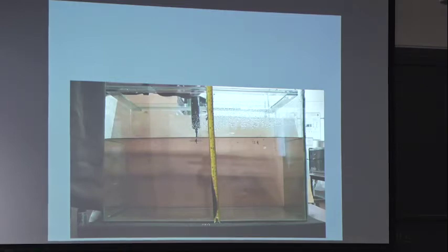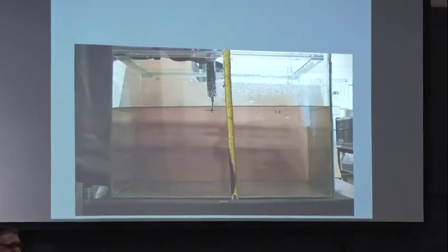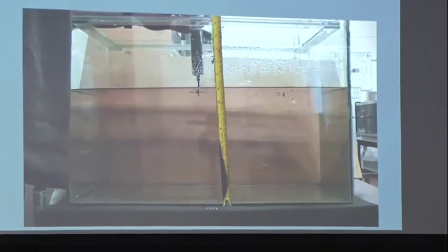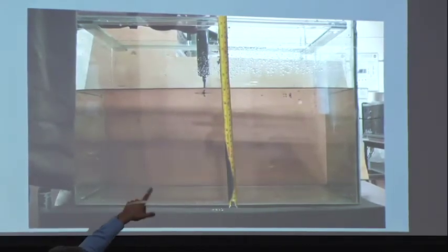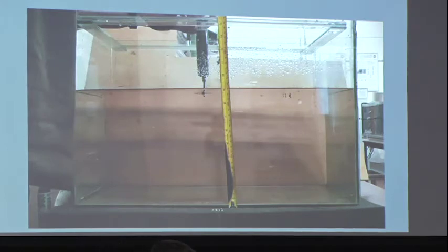Effectively you can reproduce with a salt a density gradient that is comparable to the density gradient that you will get in a fire. So what I'm going to be doing there is I'm going to inject 10 cubic centimeters of salt water, which happens to be black. The salt that we put is an ink, and effectively I'm going to make it heavier than the water.